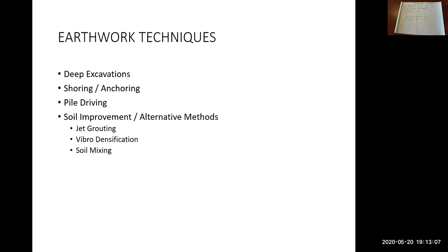So the purpose of the wood pile is to squeeze the ground into itself. So as the wood goes in, it's pushing the dirt out to the sides. So if you pound enough wood piles in, the ground eventually becomes more dense and is then able to carry heavier loads, such as a building.